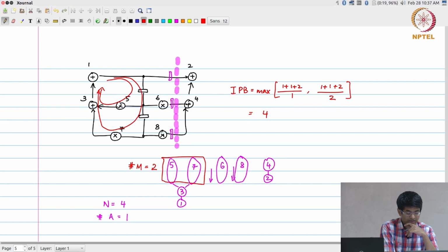Okay. So if I take that as my target, then I don't really need to worry about it. Between node 3 and, can you pipeline there? So the question is basically, is this a valid pipelining cut set? And it's not, right? Because there is this edge over here and this one over here, and they are in opposite directions. So this is not a valid pipelining cut set, right? So that's why I said you have to be careful about pipelining versus retiming.